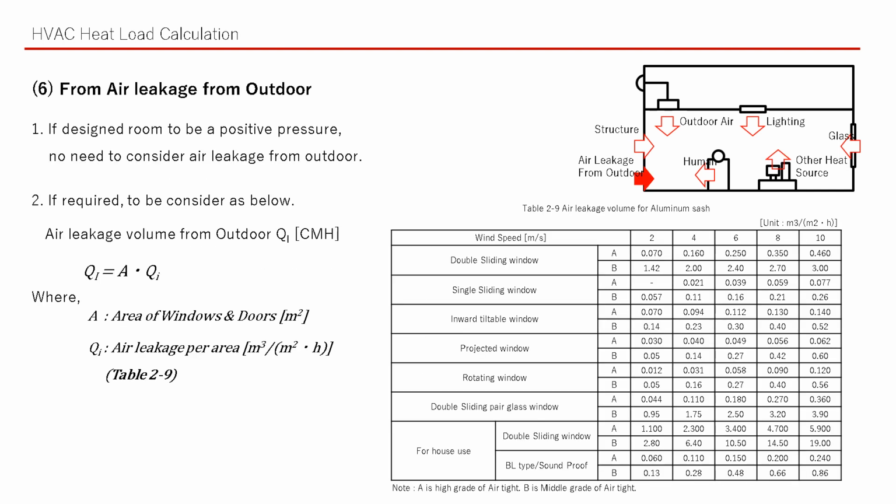We will explain the heat load from air leakage from outdoors. It depends on the air balance design. If the room is designed to be at positive pressure, there is no need to consider air leakage from outdoors. If you need to design for negative pressure, it's better to consider the heat load due to air leakage from outdoors by the following.